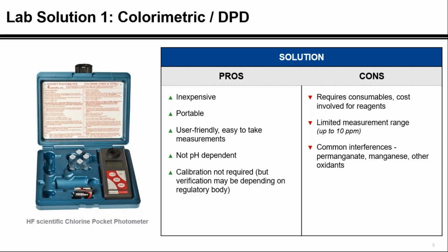Now it's as easy as pour the sample in, push a zero button, add the reagent and wait whatever the appropriate reaction time is, and that depends on whether you're measuring free chlorine or total chlorine, and press a read button, and then we have a chlorine answer. DPD as a reagent can be supplied in push-button dispensers, plastic pellets, or foil packets as a powder. It can also be supplied as a liquid pre-measured as test tubes or in a bottle with a pipette-style dispenser, or even in vacuum-sealed tubes, which suck in the correct amount of sample when you break the vacuum under the water.